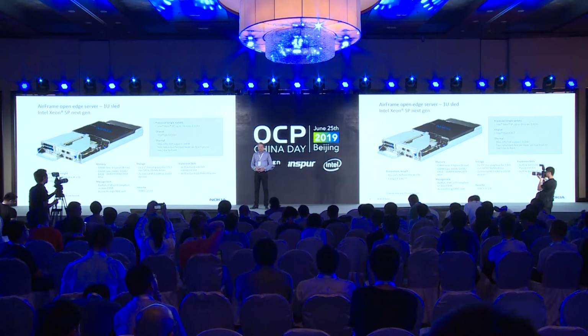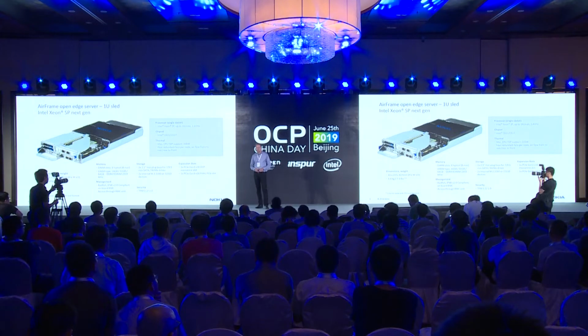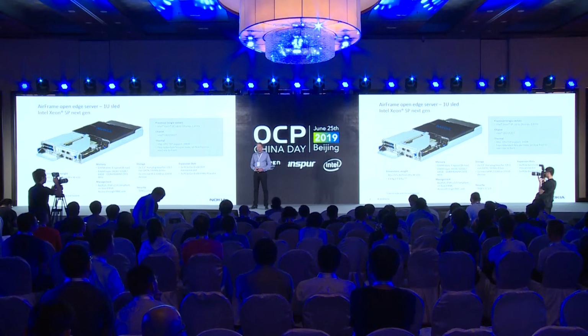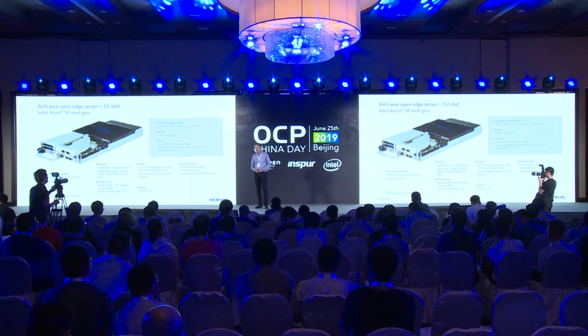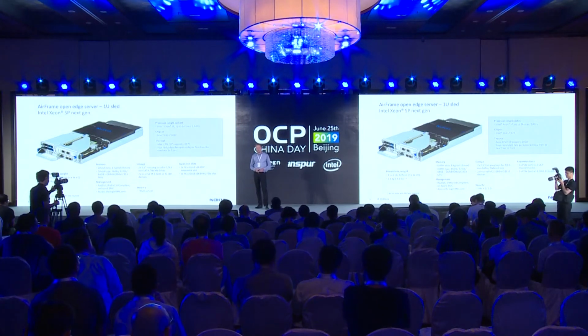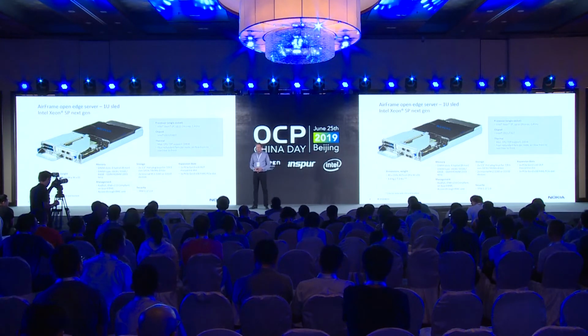The sled is half width, 215 millimeters in width and 427 millimeters in depth. And like typical Purley designs, this has 6 memory channels, and actually 8 memory slots. We are supporting also 2 additional slots for non-volatile DIMMs when those are needed.